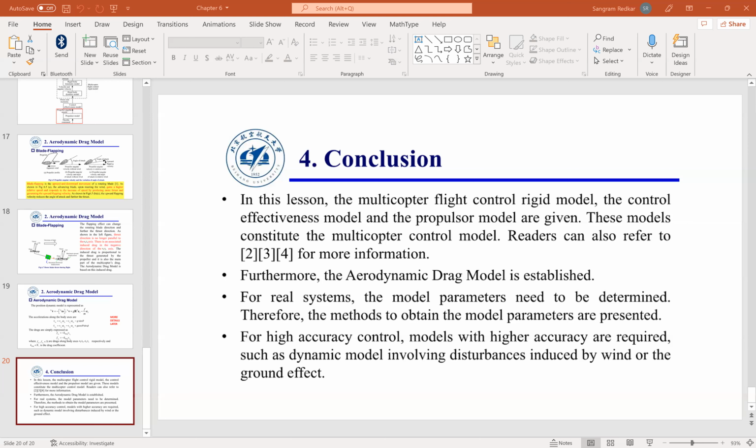The Jacobian for the region and the Jacobian for the location are the same. No, yeah, they are different. How different? For the same maneuver. Linear is going straight. Rotating is... for the same maneuver. Whichever same maneuver, the Jacobian for that maneuver is the same with the case of rotation and the case of... Jacobian for translation is defined differently than Jacobian for rotation. If you look at the way we derived in robotics 1, Jacobian for translation is different than the Jacobian for rotation, even though the motion is the same. The only thing is if you are in level flight, then they may be the same, but otherwise they will be different. As soon as you have angular orientation, they will be different.